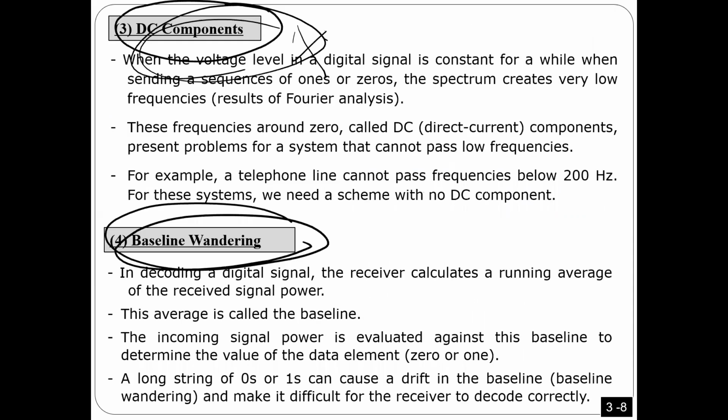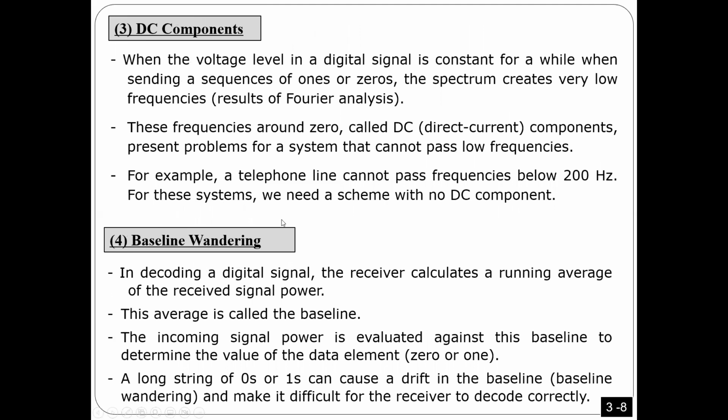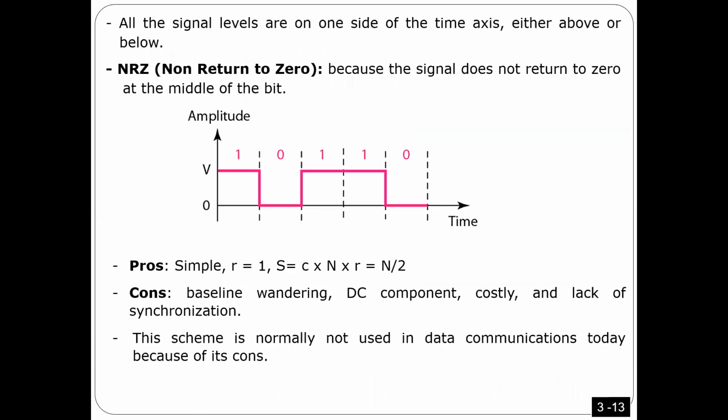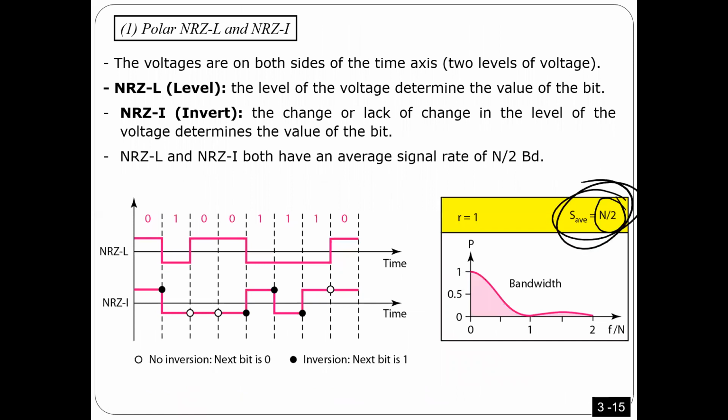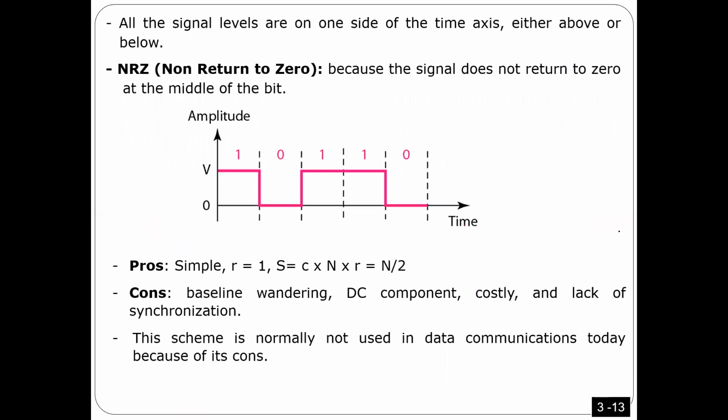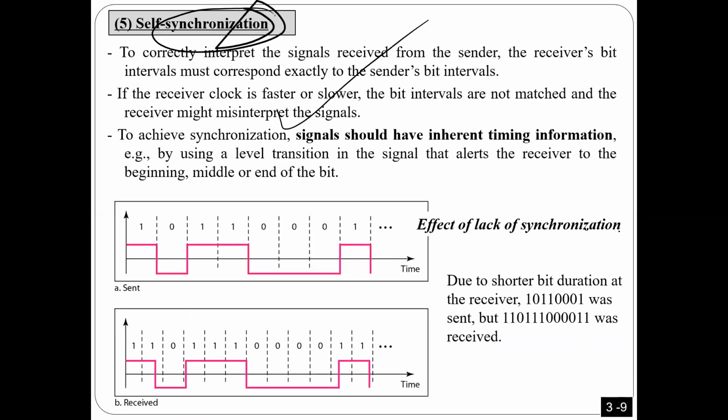Okay, so now I want to move to the next. So again, every time I teach an encoder, I'm going to tell you what the bandwidth is. Okay, that's what you will see later. You will see here I always give you the bandwidth. You should keep in mind the lower the bandwidth, for sure, the better. For the same bit rate, if I need a small amount of bandwidth, it is going to be better. Okay, this is a metric I'm going to use between different encoders.